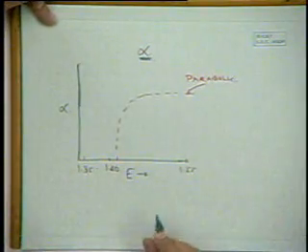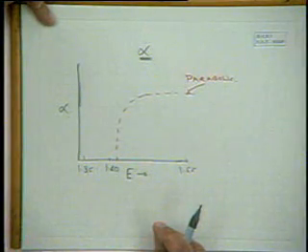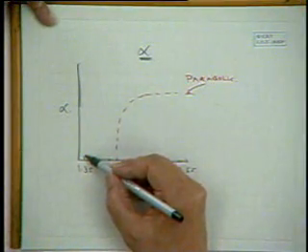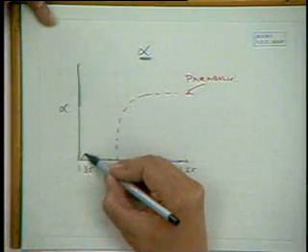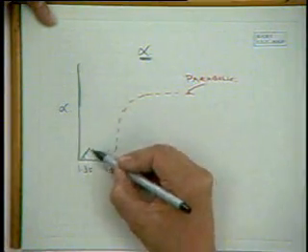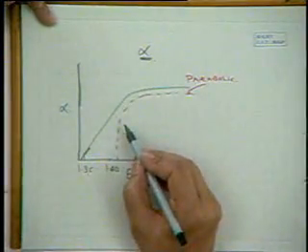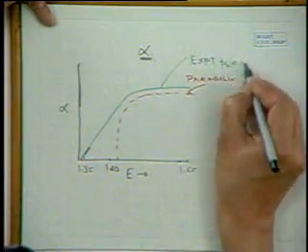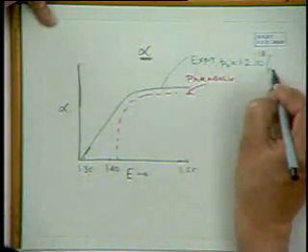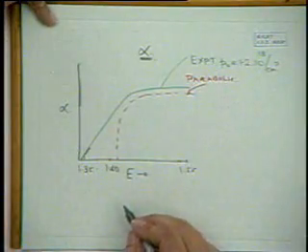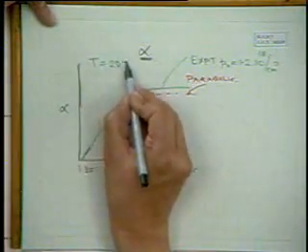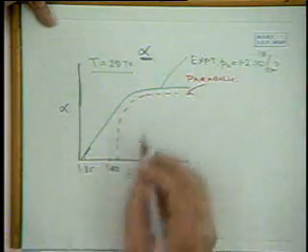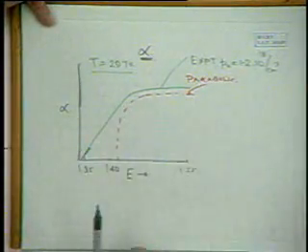Let's compare this with experiment. With experiment, we find that the experimental results are quite different. This is experiment. P0 is reasonably heavily doped, 10 to the power 18. Okay. So temperature is important. T is 297 K. So you see there's wide divergence between, not only is the shape different, the cutoff energy is different, the saturation is different, the whole nature of this optical absorption is different.